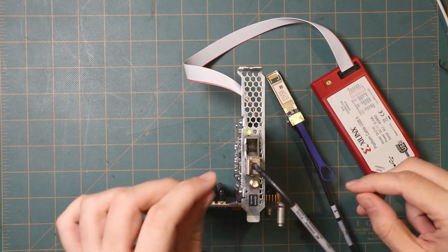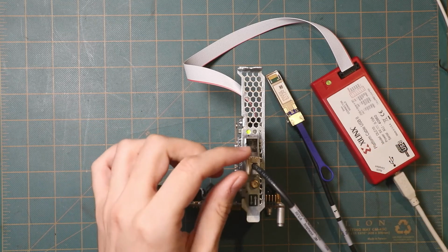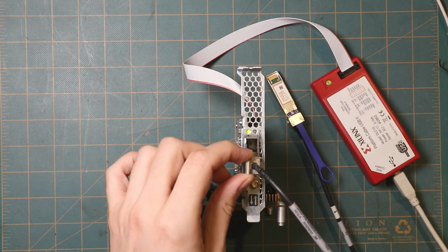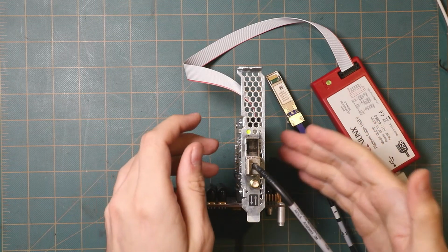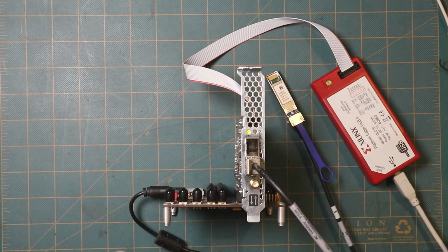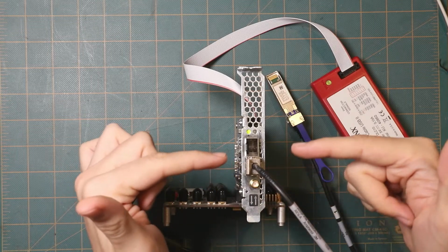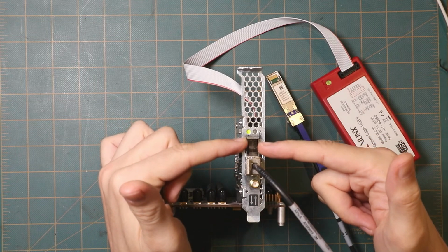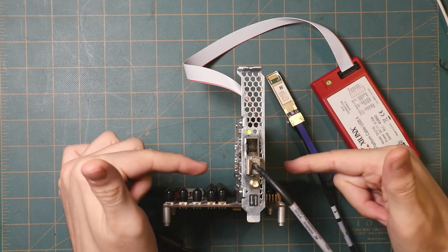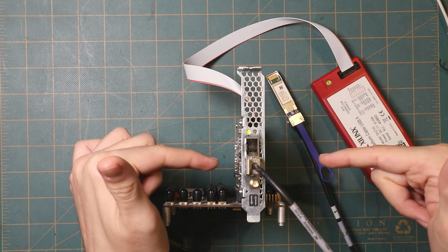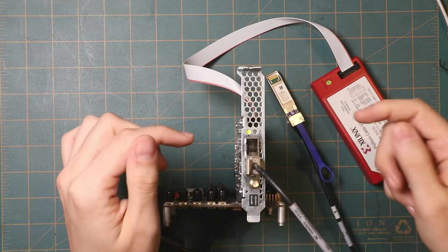What we have hooked up to this is a connection to a 10 gigabit NIC in my desktop computer, and the design running on the FPGA is basically an instrumented version of my Verilog Ethernet design. It has PHYs on both of the ports here, and connected to this one there is a 10 gig MAC and then the UDP stack.